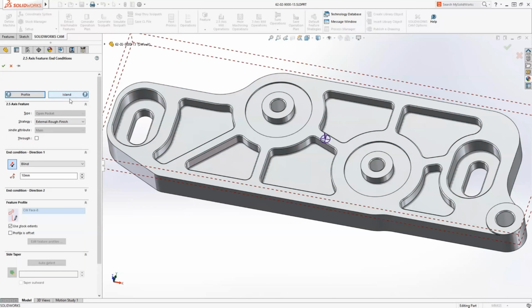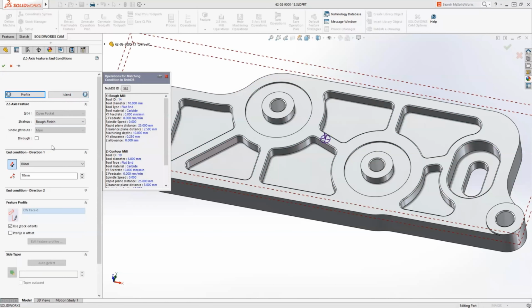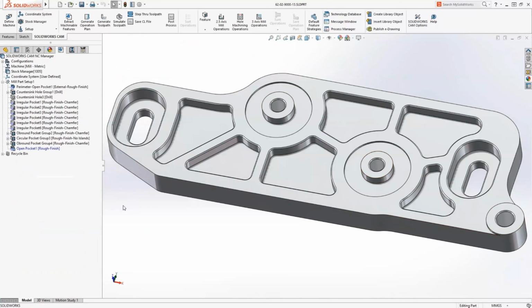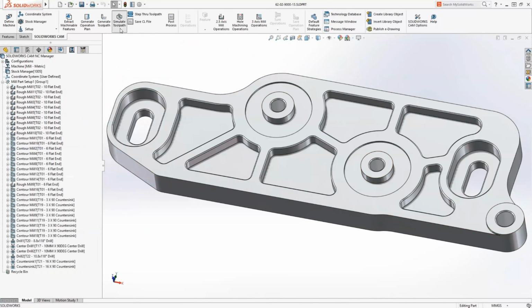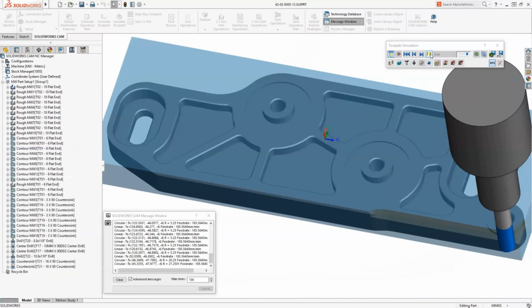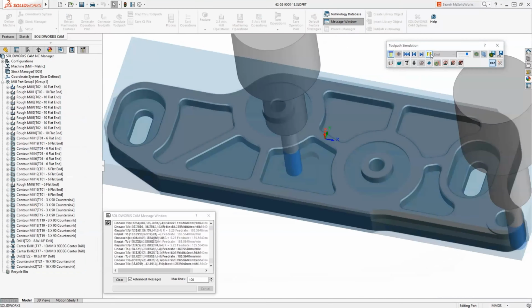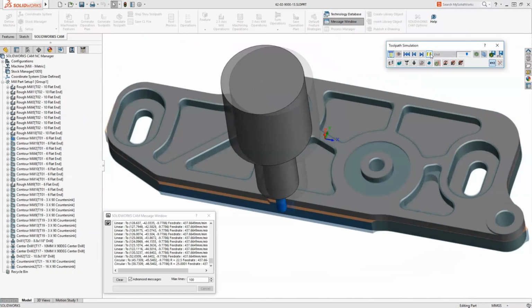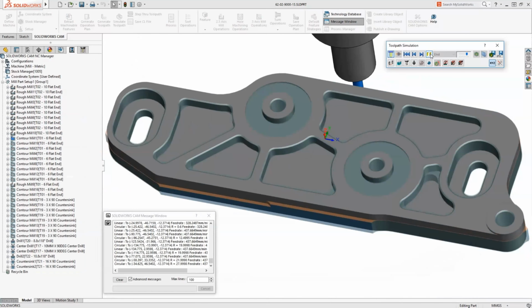So all I want to do from here is just create for myself a rough model. So the raw material I'm going to buy, and just select what phases I'm going to work from. So with a few simple clicks, I can start machining. So SolidWorks CAM has automatically decided what tool it's going to use for what cycle.